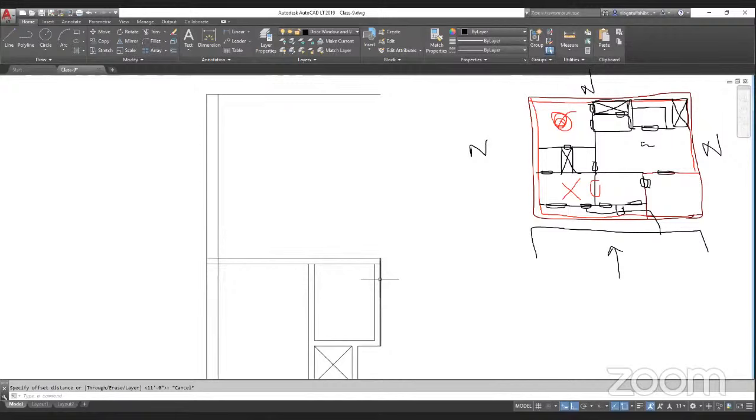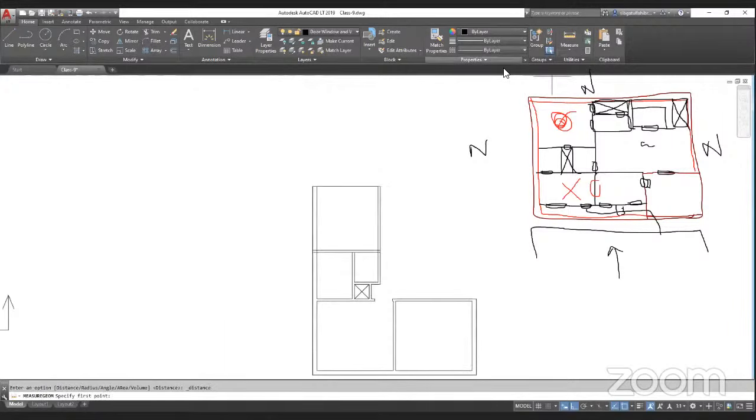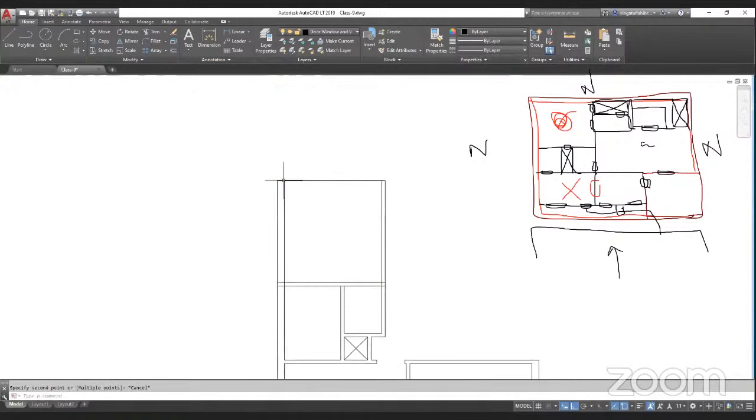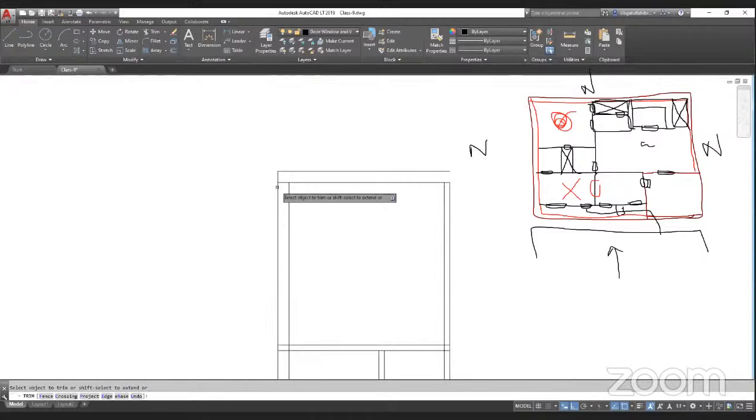Okay, so this will be the next bedroom, and the size of this bedroom is 11 feet and this is 10 feet 5 inches. Yeah, that's more than enough. And this is the outer wall over here, so 9 inches, like this. And then using the trim option, TR, enter, I'll just extend this line and trim this line. And then the same thing happens over here as well.